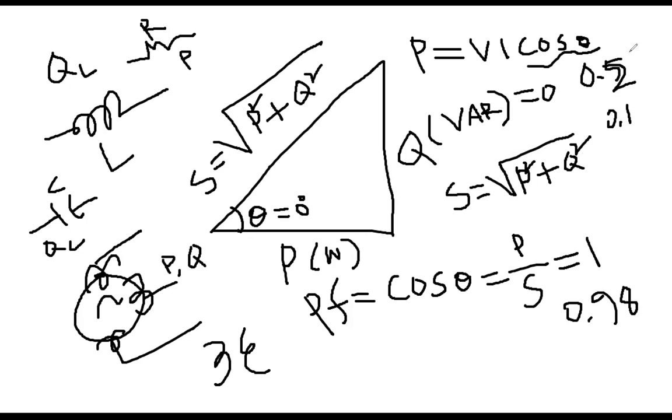On the other hand, if you can increase in this way, and if you can make the cos theta value 1 or close to 1, that time you are getting the highest power, this power in watts, because that is useful in real life. So Q is not useful in real life. It will just cause heating in the system. So everybody, could you follow what I am explaining?